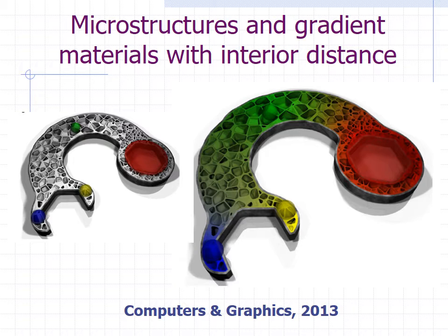This method allows for the definition of material sources as geometric objects defined by continuous scalar fields, and therefore using internal distances and Voronoi diagrams together achieves intuitive results for the user. In this example, four features were used to control the attributes of the foam structure, which are average cell size, wall thickness, and roundness. So, after using interpolation, the scalar fields influencing the resulting shape parameters were obtained. The large red feature uses a small cell size, large blended value, and thick walls. The green feature contrasts with narrow walls, practically no blending, and ample cell size. The last two features, yellow and blue, have high blending and thick walls.